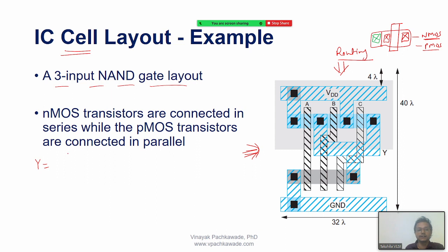What is that cell? It is just some logic, and the logic is y equals a and b and c, and it's a NAND function. So I know that the schematic of this NAND looks like something like this. This is, let's say, A, B and C, and I know that I have to use these parallel transistors of the PMOS right over here, right over here, and then I have this VDD, for instance.